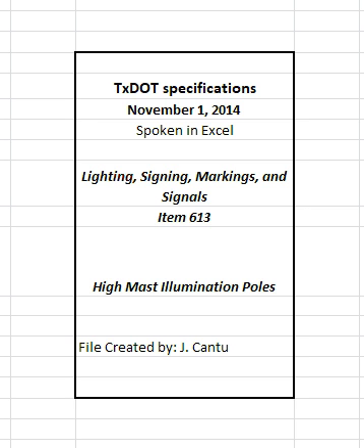Hold conduit in place with a bar attached to the upper template and cap conduit before placing concrete. Ream conduit to remove burrs and sharp edges after placing concrete. Install bell ends or bushings on the conduit.